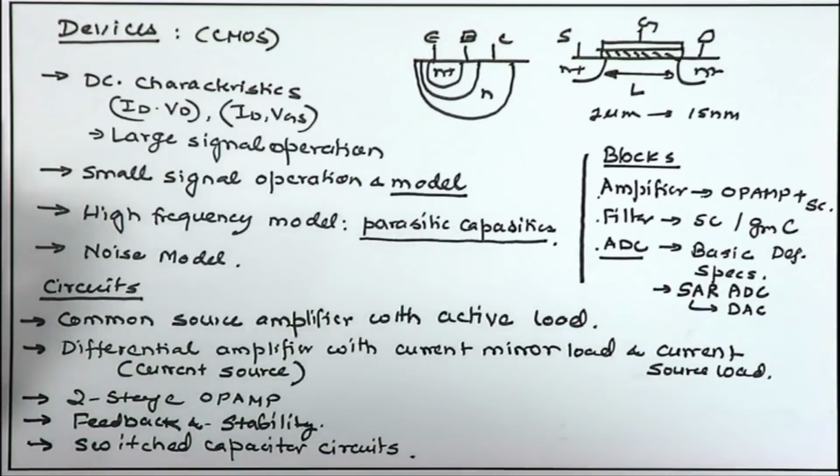What are the challenges, what are the different aspects that we need to address while dealing with different applications. So, first thing is signal characteristics. In this particular application, we are dealing with biomedical signals. There are many different kinds of biomedical signals which can be acquired with different kinds of sensors. So, there itself the characteristics of the front end, the kind of analog signal processing you can do, the kind of front end amplifier, filter, ADC you are going to have is going to be very different. It may not be as simple an analog chain like this. You can have many different functionalities embedded into the analog chain itself.